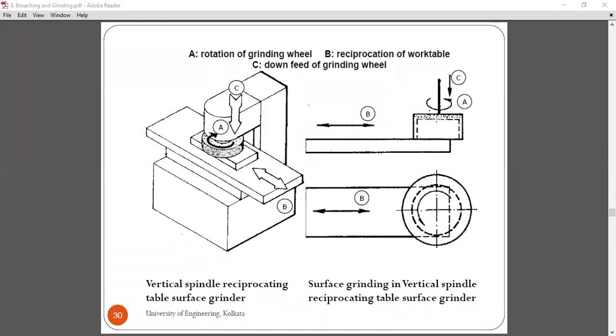material properly. So if you see the front view of this, you will be able to understand the situation. This is the front view of the process, and this is the top view. Okay, so we will be able to understand how the grinding process takes place. So this is the rotation of the wheel, and as the wheel rotates, this table or the workpiece reciprocates, so material removal takes place from the entire surface. Okay, so this is the top view, you can understand.